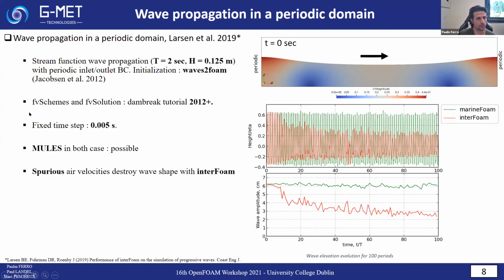And we are using the schemes and solution of the dambreak tutorial. This is the methodology of Larsen. And we use MULES in both cases, for marineFoam and interFoam, in order to be as fair as possible. So this test case will only show the advantage of using the Ghost Fluid Method. What you can see here is that with marineFoam, the wave height, or the wave amplitude, is better predicted during the wave traveling. Here you have 100 periods, so 200 seconds of simulation time.